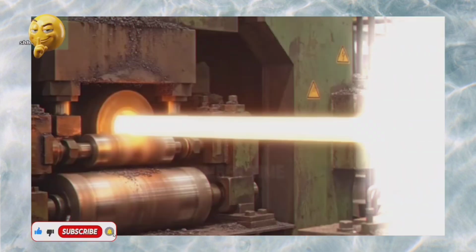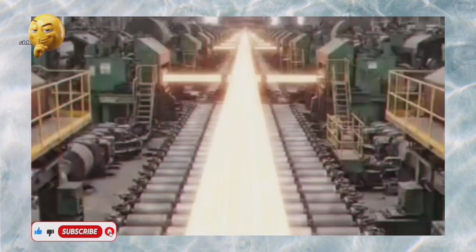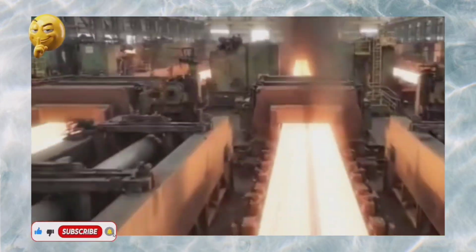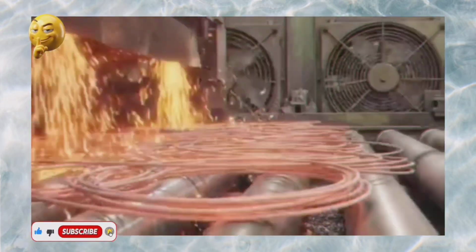The red-hot billet passes through a series of high-speed rolling stands. Each stand reduces thickness and increases length. The steel moves faster and faster, sometimes exceeding 100 kilometers per hour. Gradually, the square billet becomes a smooth, round wire rod with precise diameter.